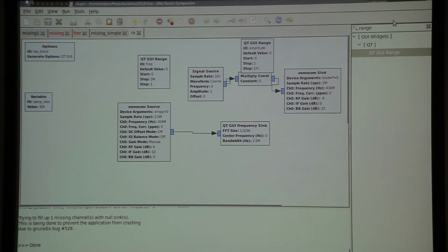So strictly, you have to be a little bit careful with what you transmit with SDRs, especially when you have transmit capability, because they will not stop you transmitting on frequencies you're not licensed to transmit on. In this case, we're operating in an ISM frequency where we are allowed to transmit, and these only put out 10 milliwatts, so we're not doing anything naughty. In more serious cases, you might want to start thinking about using an amateur radio license, or not using antennas at all, and then it doesn't matter so much.